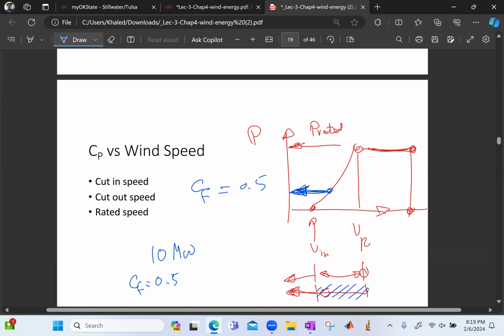Just like that homework problem that we just did. We calculated the CF from the actual power. How did we calculate the actual power? It's the number of hours you stayed in that wind category times the power from that turbine at that wind category. You multiply two numbers. Site available, turbine produces enough power at that place, at that wind speed, right?